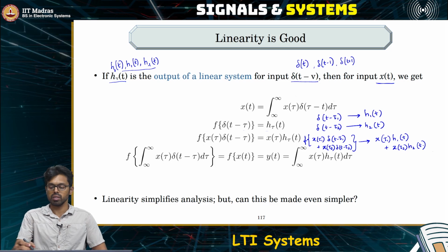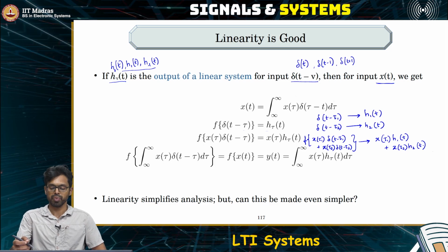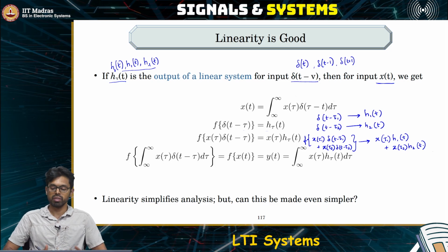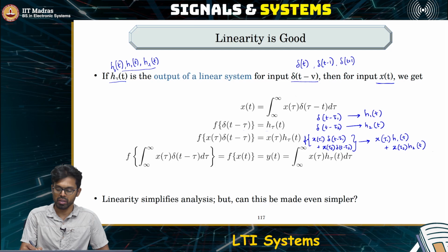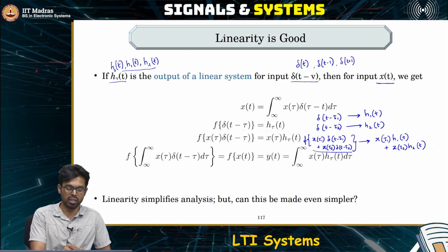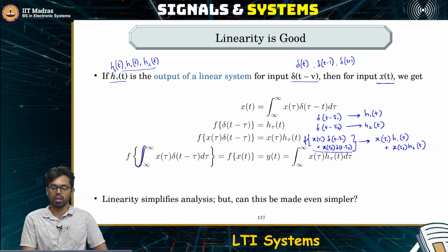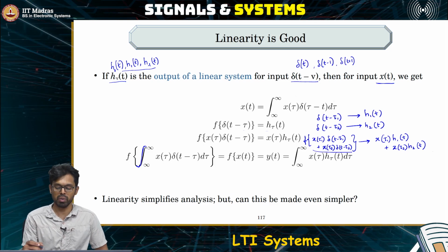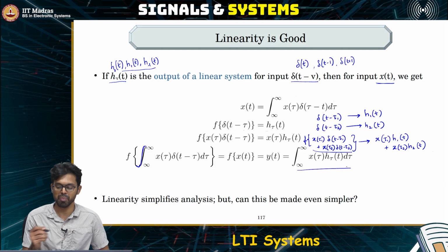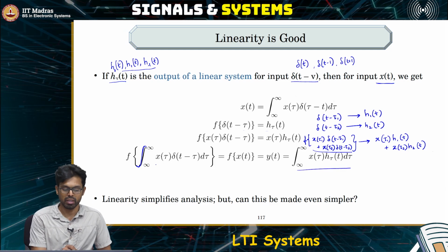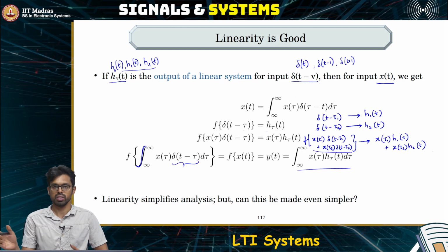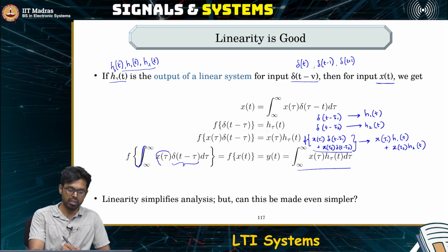So this is when the input has two signals. The additive property comes as such. What if the input is a sum of infinitely many? So the summation here is basically an integration, and that summation still is retained because of the linearity property, and exactly that's what happens here. So you take the sum of multiple Dirac delta functions which are all shifted in time and scaled.